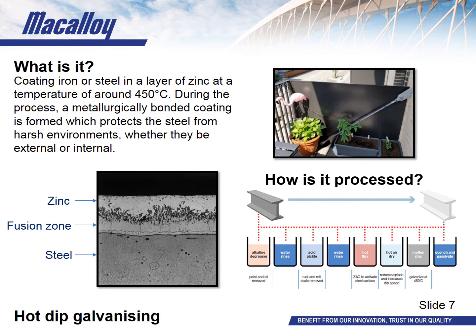After further rinsing, the components will then commonly undergo a fluxing procedure. Now this is normally applied by dipping in a flux solution which is usually about 30% zinc ammonium chloride at around 65 to 80 degrees Celsius. Alternatively, some galvanizing plants may operate using a flux blanket on top of the galvanizing bath. The fluxing operation removes the last traces of oxide from the surface and allows the molten zinc to wet the steel.